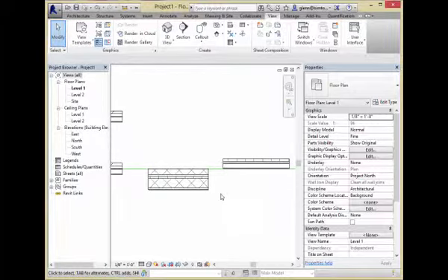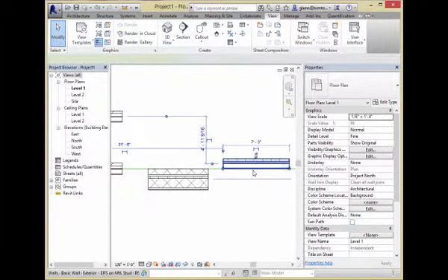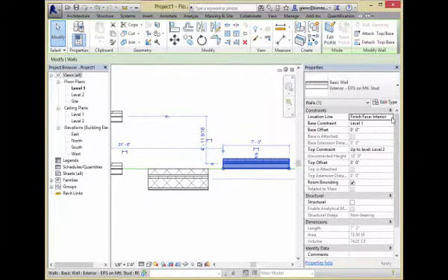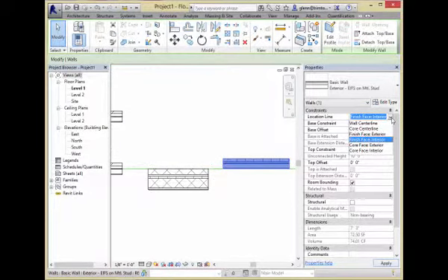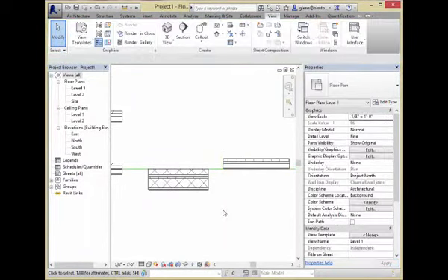That has been fine so far, but if I want to go through and change this wall now, but have any change hold constant so that stud layer always stays in the same place, so it doesn't shift around relative to the foundation, what you can do is this. Choose that wall. One of its instance properties is whatever the location line is. You might want to change that. And I can say, great, I want the core face exterior to be the location line.